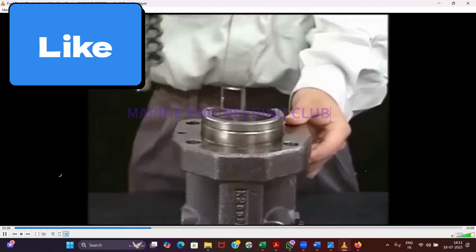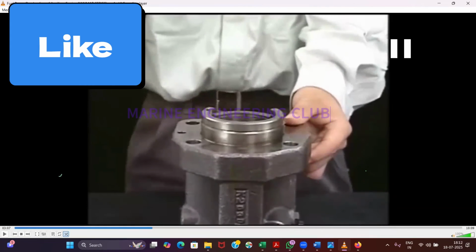See, right? Down below, what you will be having? The upper spring carrier retainer. Agreed? Yes. Below there is the spring retainer. Remove it, and then with a tong or something you can remove your control sleeve also, out of it.